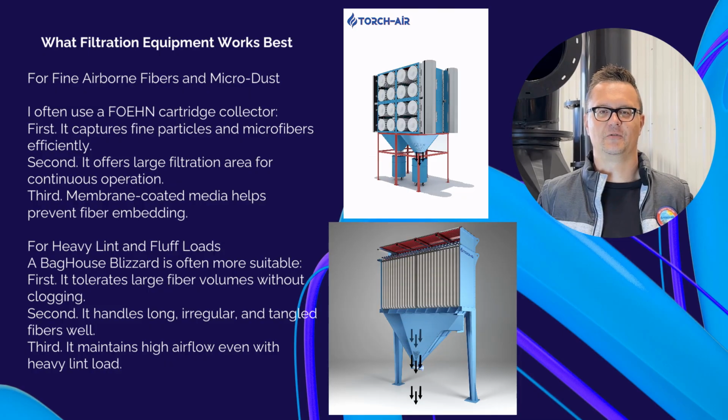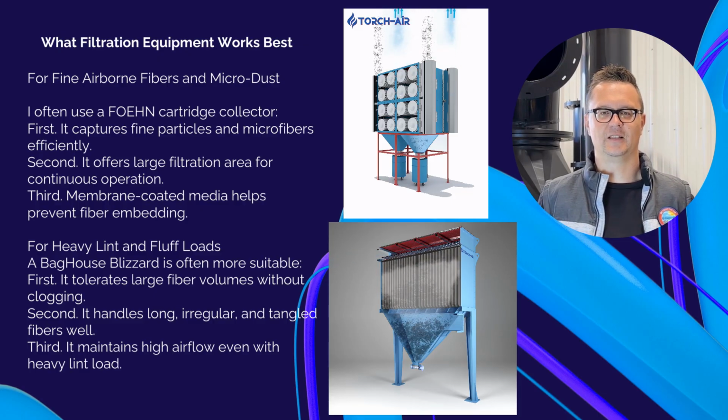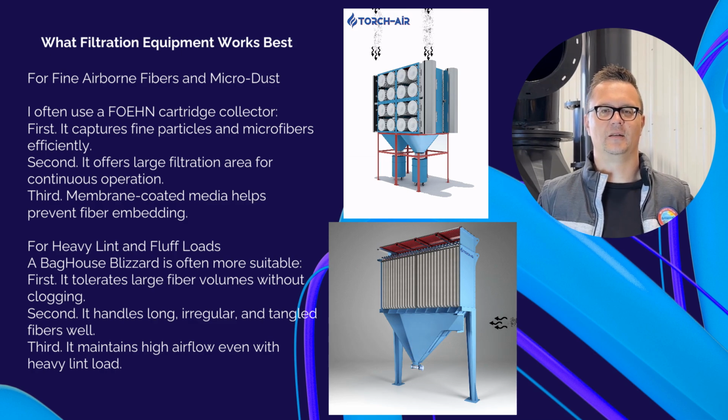For heavy lint and fluff loads, a baghouse is often more suitable. First, it tolerates large fiber volumes without clogging. Second, it handles long, irregular, and tangled fibers well. Third, it maintains high airflow even with heavy lint load.